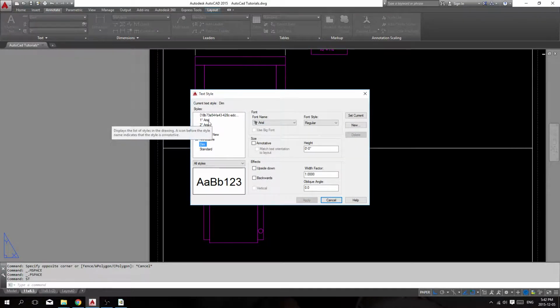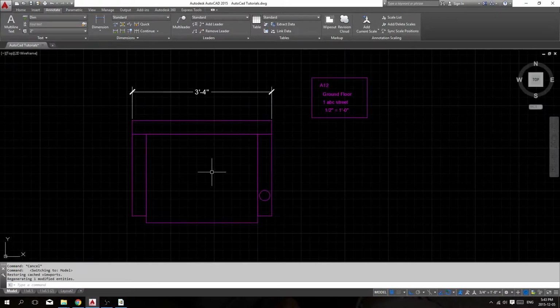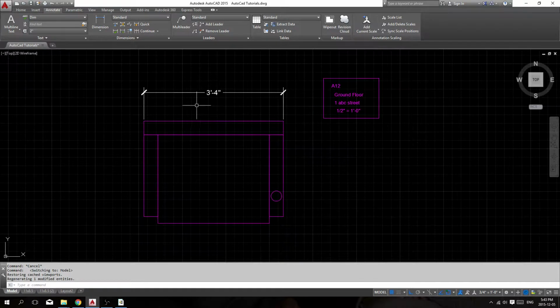So from now on, let's say half inch is 1 foot, 3/4 is 1 foot, we'll create those. So when we're adding letters, it will be the same thing as when we're dimensioning it. Our dimensions will be the same. But that's enough for right now. The next video, I will do the math, how we're gonna get the fit and the text size when we're noting the drawings. There's a formula, like an easy formula. We'll use that to get all of our fit numbers and the text size when we're dimensioning.